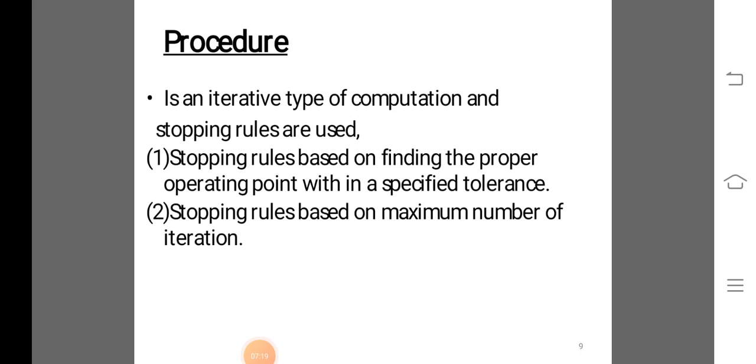These schemes work well in computer implementation where the execution time for the economic dispatch is short and will always give consistent answers when units reach limits, pass through a breakpoint in a piecewise linear incremental cost function, or have non-convex cost curves.